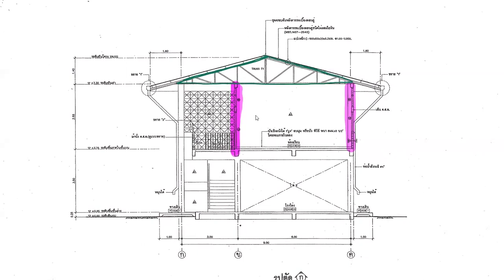Okay. There is this part that is not clear and I don't like, because if you extend this portion out of the truss, your top chord member will no longer act like a top chord member because it's going to have bending moment. So let me clear the overhanging portion the way Suchat wants you guys to do it. Okay, so there we go. Your first headache: you're going to have a truss that is not really symmetric. It looks like that.